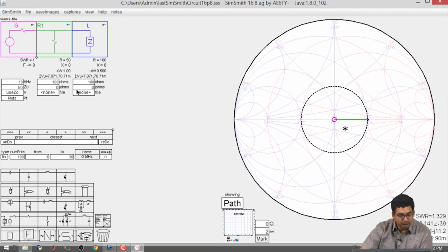Okay. So, now the circuit is impedance matched, standing wave ratio is only 1, reflection coefficient is 0, but I still have only 0.5 watts at the load. So, once again, by adding a resistor, you moved along the line of constant reactance. In this case, the reactance is 0, so you moved, but adding a resistor comes with a penalty in terms of the power that you can get at the load end.